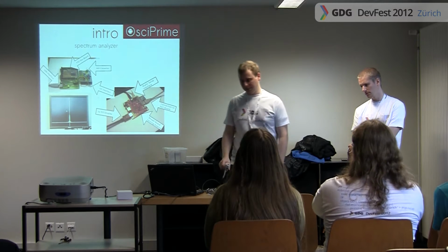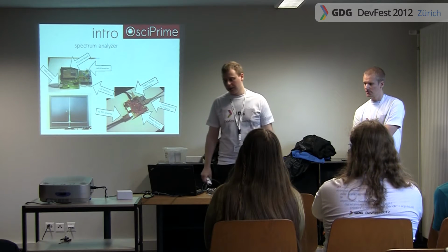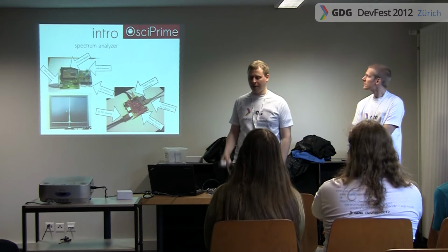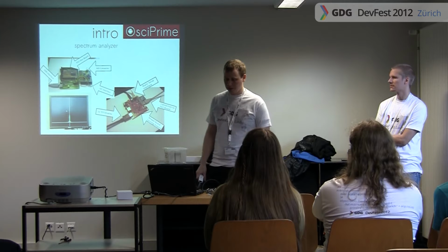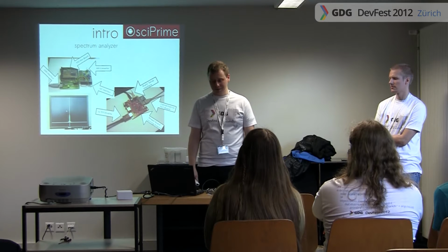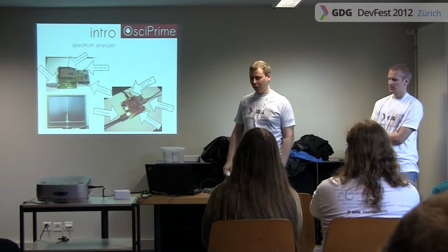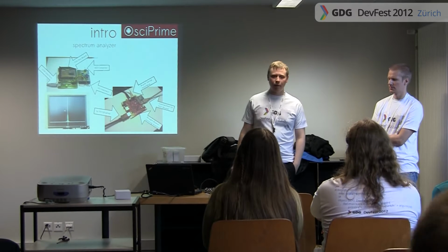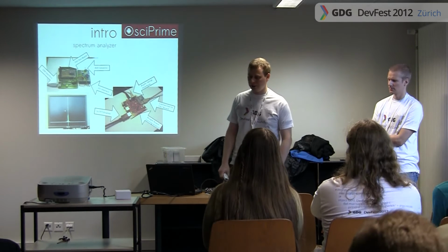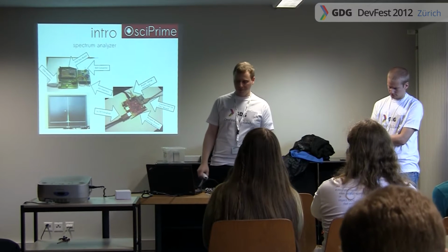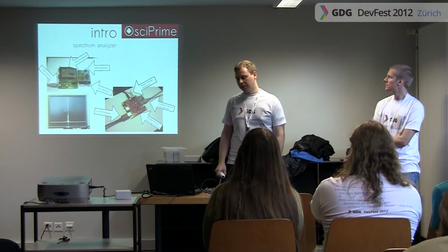The project looked like this. On the bottom right, you see the BeagleBoard, which is our hardware platform. We have an OMAP controller there, and we have the Android source, or an Android build, running on top of there. Then on the top left side, you see a picture of our data acquisition front end. This is a dev board for USB programming with a Cypress FX2 microcontroller, where we learned to program USB. And we attached via I2C interface a very simple AD converter.